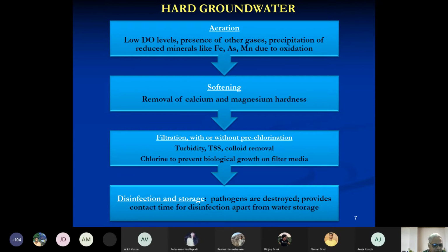And after a significant period of time, you will find that the rod has changed color from a steelish color to white, really white. And that white comes from precipitates of calcium and magnesium. So over a period of time, you get a scale of calcium and magnesium on the hot rod or any other heating appliance.